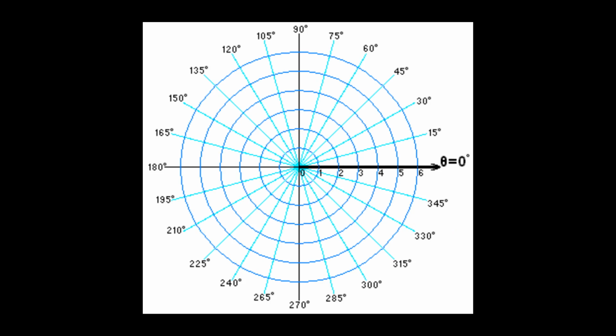There is one other coordinate system that we need to talk about, and that is the polar coordinate system. We don't always draw everything horizontally and vertically. We can draw angled lines by using our reference coordinates from an absolute point or an absolute point to an absolute point, but sometimes that's not the information we're giving. Sometimes we're told how long a line needs to be and at what angle it needs to be. So to be able to do that, we have to use our polar coordinates.